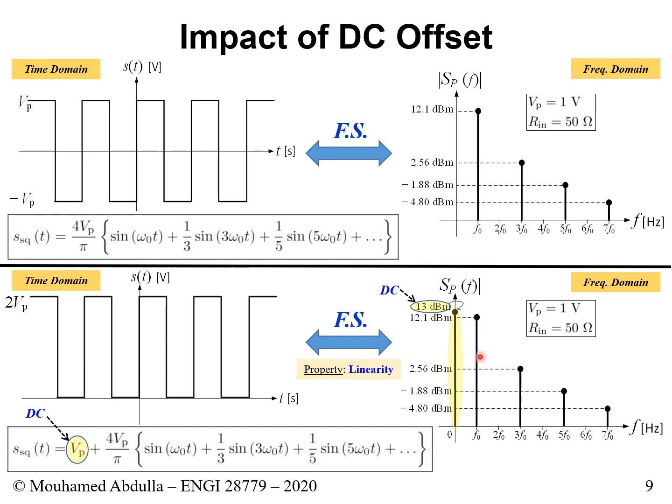Remember when we got the power for the others? We went through 5 steps, right? Step 1 was to determine the peak value of each sinusoid. Step 2 was to find the RMS value of each of these peak values. Step 3 was to determine the average power. Step 4 was to find dBW. And step 5 was to find dBm, which is by simply adding 30. And we got this formula that we derived in lecture 3, which is 20 log10 of Vp minus 10 log10 of input resistance plus 27.